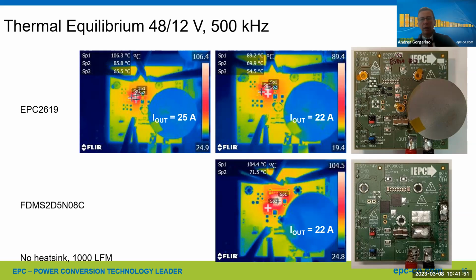That's why a lot of silicon devices trying to reach higher frequencies have what they call a Kelvin source. That means there's a separate wire bond to connect to the source, to eliminate the package contribution to that common source inductance. The advantage of GaN is there are no wire bonds. You have direct access, basically a few microns away from the actual source of the gate. And so you have the minimum possible common source inductance. Now, when you put it on your board, you need to make sure that you don't create common source inductance.